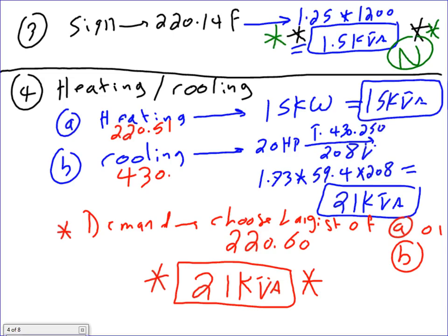Heating, cooling. Now that's neat thinking. Are my heating and cooling 3-phase or single-phase? 3-phase. Do I need to carry anything from this here? No. Why? All these 50 kVA, I assume, should be all 3-phase. This is all 3-phase balanced. Do I need to worry about it? No. So I'm going to write myself: no neutral load here.